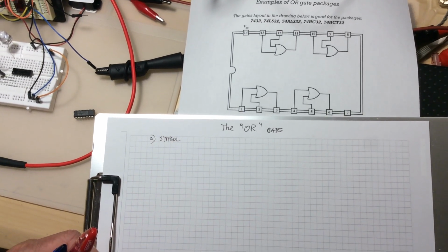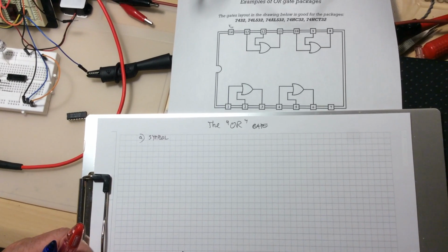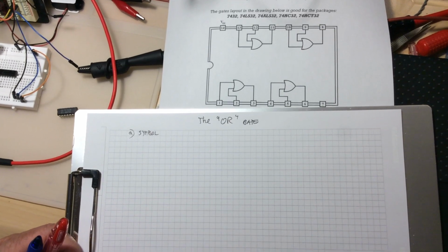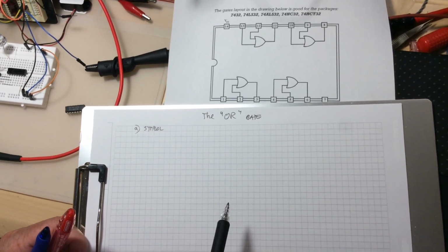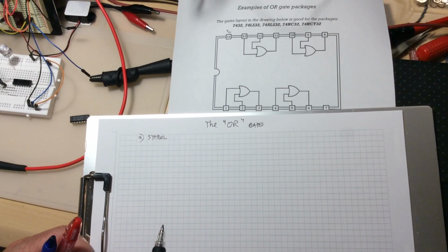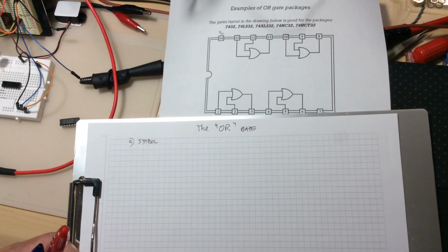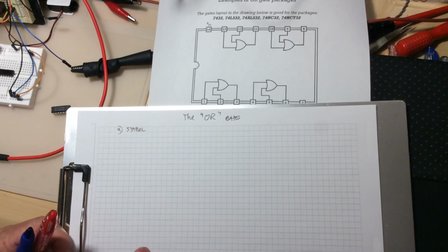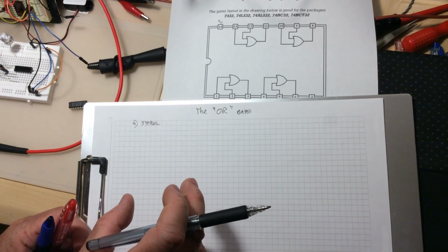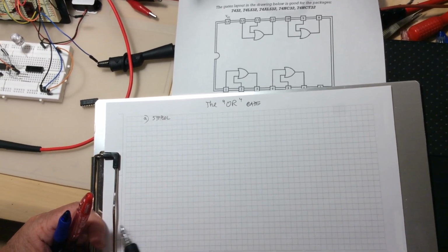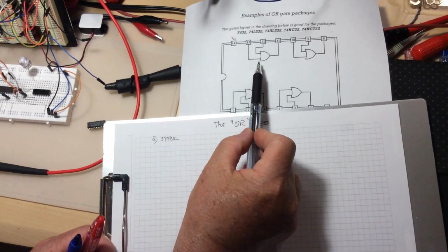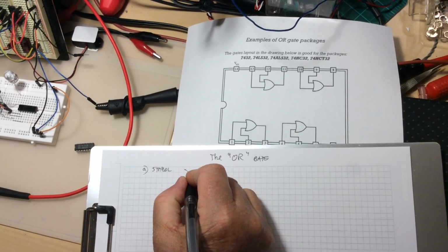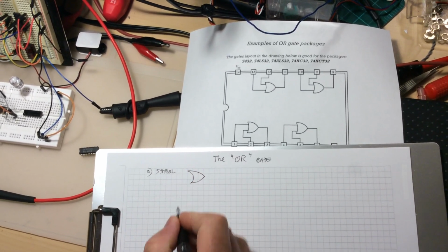As you know, all the gates starting with a simple inverter contain 4 to 6 transistors or more. So there is no purpose to start drawing such a handkerchief, plenty of transistors around. So for that reason, the whole diagram is considered something like a black box, and the engineers just tell us what that black box does and what is the symbol for it to recognize it. So this, what you see here, is the symbol for the OR gate. I'm going to put it here. So you are going to draw something like this.